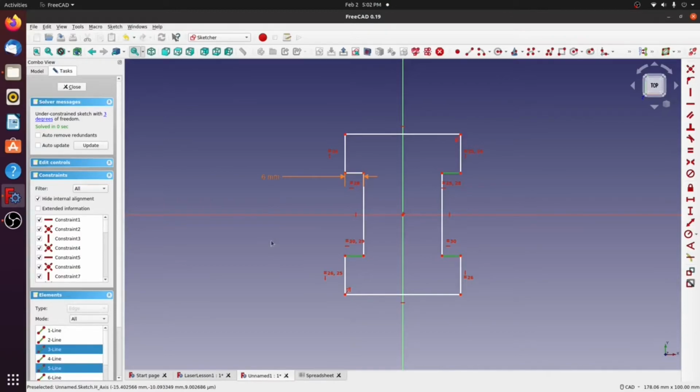This has a lot of implications because it means that you can start using the same models. And if you're on, say, like a diode-based laser and you're working with thinner stuff like cardstock, well, you could just go in, you could set it to like a 1 millimeter or 1.5 millimeter. If you're on a more powerful laser like we have in the space, like say the Omni, you can go up to like 6 millimeters, maybe even more. And so simply by changing that number, you can recompute your model for the material that you're working with.